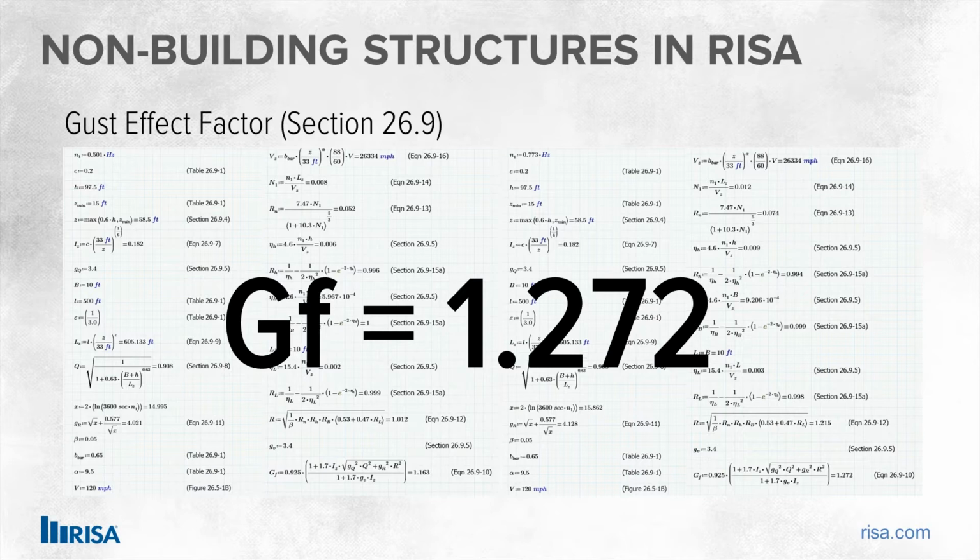Now I actually took this as an envelope between the lowest frequency and the highest frequency of all the fundamental frequencies in the structure to make sure that I was capturing the highest gust effect factor.